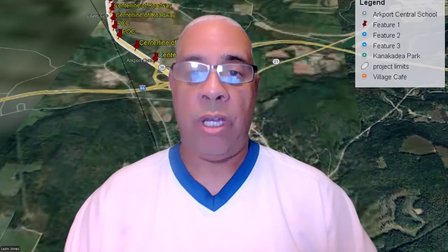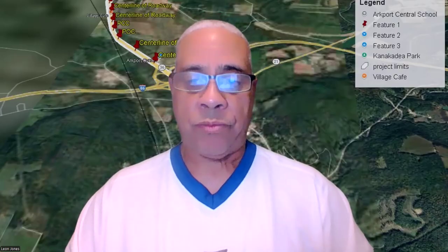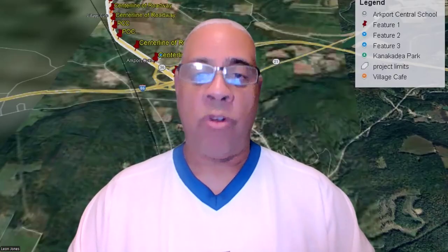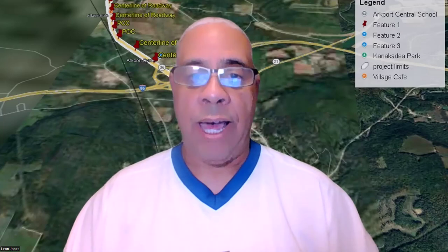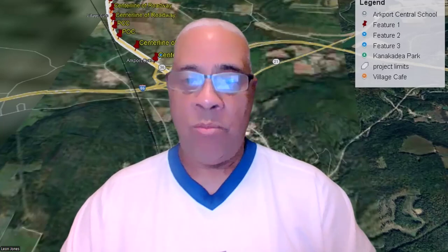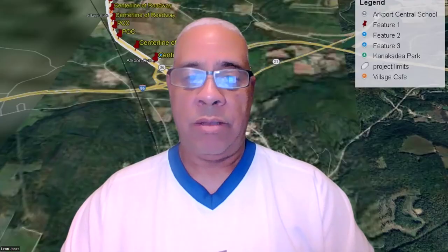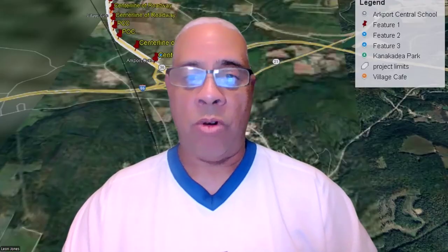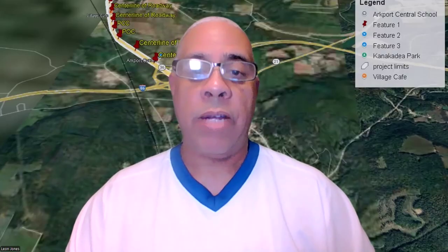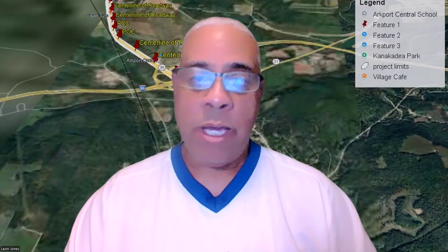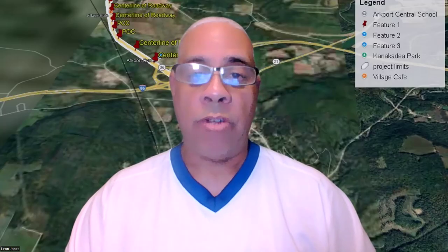One guy actually doing the legwork for you by putting the laths together. The laths are the stakes, marking the laths, putting the tape, go out and stake it. Now, there are times where you're going to send somebody out there, you're going to have a prism, but you can set a robotic instrument up. But GPS is what everybody's going to.